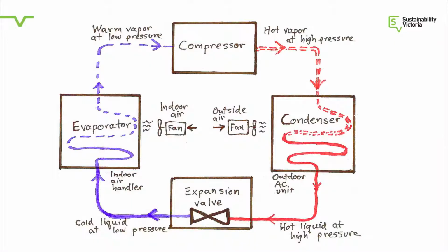Now, refrigeration in its simplest sense has four components. I need to explain these because how systems use energy depends on a basic understanding of refrigeration. This little diagram already shows that. We have a compressor, a condenser, an expansion valve, and an evaporator. Every refrigeration or air conditioning system will have those four components. So we'll start with the compressor. Now remember, it's a vapor compression system. That's the fundamental principle here.